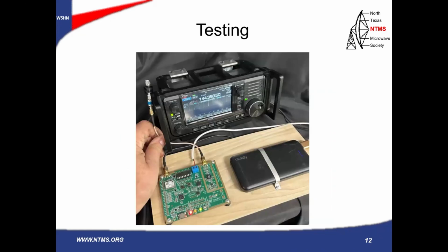Here's my test setup. Let's talk about this. This is the RF0 board to the lower left. You'll see 3 LEDs. There's a red light that's going to key on transmit output. During WSJT, it will be half the symbol rate. The yellow light is the 1 second register from the GPS, and the green light is the GPS active and good.